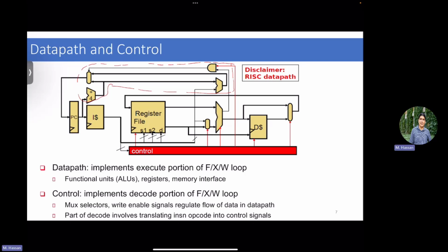Because with a program counter, usually you increment by 4. But if you have a control flow instruction, like a branch or a jump, then simply you need to add some extra logic. You need to load in the offset or the address into that, right? And I only do this for a branch or a jump instruction. That's why we need some enable here that will come later on. But as a whole, that's the part of the circuit that tells what program counter next I need to read. It's either program counter +4 for the next instruction, or my jump address or my branch address if I have a branch that is taken.